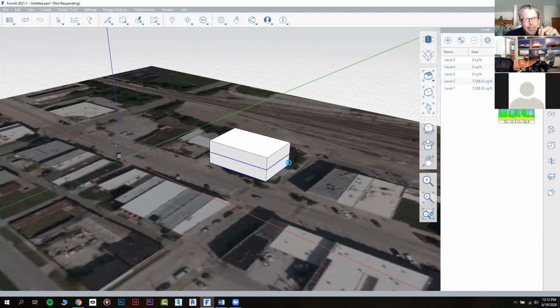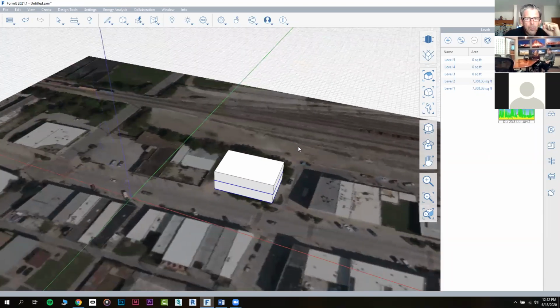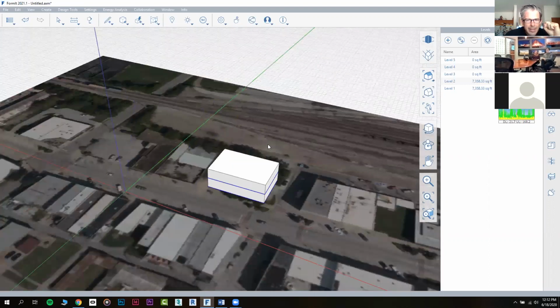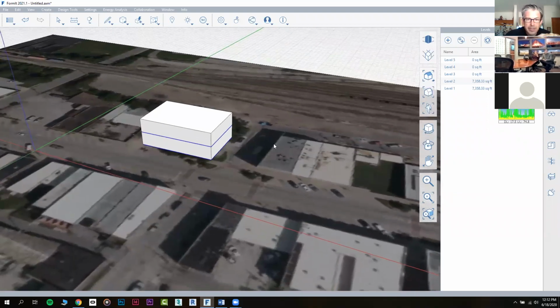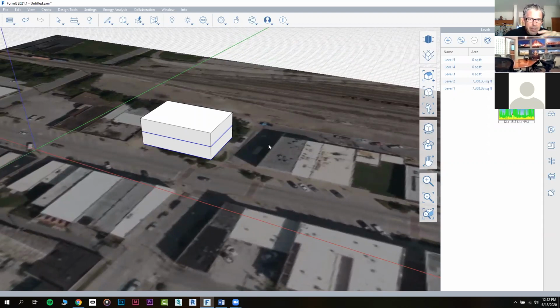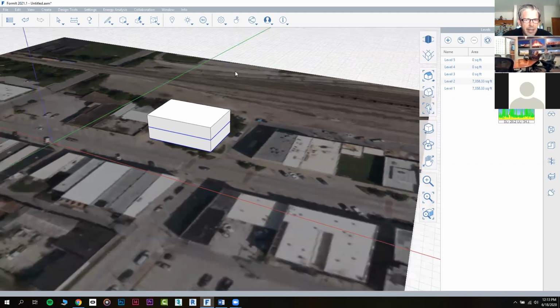When we did Insight back in the day, there were a few things that we went in and prescribed even further, like the building types and things like that. They've kind of reset that a bit anymore. Now, it's not really about building type. This is such early phase simulation that it's much more about beginning to build some generic data based on standard buildings. As the building develops, you're really moving into another tool set, Green Building Studio in particular, if you're in the Autodesk panel, to begin refining that data. This is just about getting some baseline information put together.